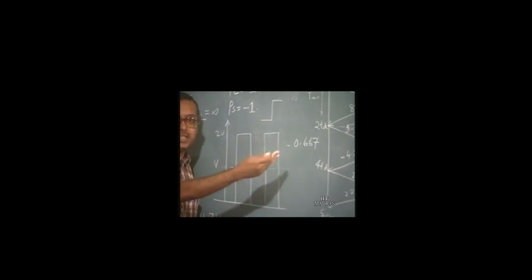Now, in the actual circuit, if this is going to drive the clock of a flip-flop, for example the clock of a shift register, you expect there is going to be one single shift, but what you get is a number of waveforms, and the shift register will see a number of clock pulses at the input, so that there are going to be multiple shifts. So all that you have designed in the circuit is going to go haywire, and you are going to get something totally unexpected, and you would not know what is happening. But of course, this is the extreme case.